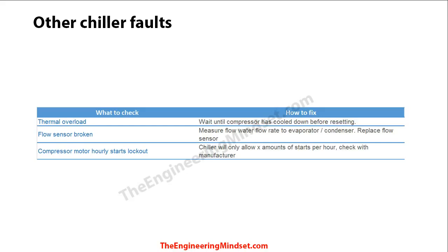And this is to protect itself and also all your electrical equipment, as the inrush current for these chillers can be very large, and large enough that it will damage your electrical equipment and distribution for your building, as well as the chiller motor or motor winding. So if you've got a low loading and your chiller is not turning back on, then this is likely the reason why.